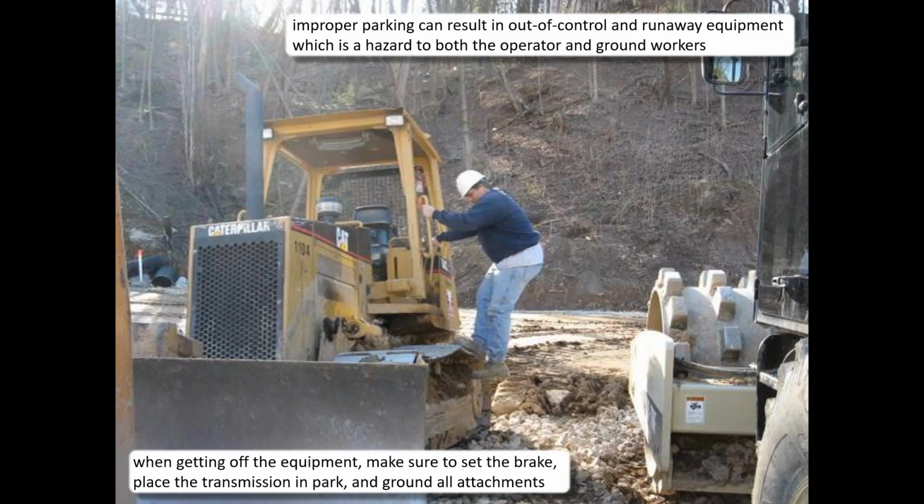What I do see a lot of statistically, the most common injury I see from my heavy equipment operators is from them jumping out of the cab. I have a lot of knee injuries and shoulder injuries and ankle injuries from operators basically jumping out of the cab. So in addition to parking it in a good place, so we don't get things rolling out of control, we've got to get people in the habit of setting their parking brake and dropping their attachments to the ground. We also need to really get in their head the 3 points of contact.